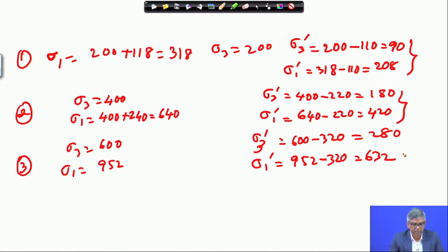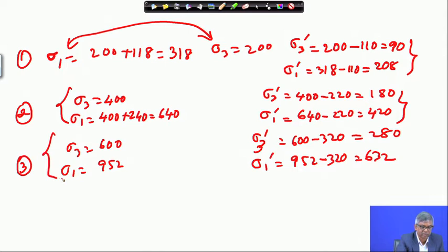So, we are getting sigma 1 and sigma 3 in terms of total stress, one set for each test. That means I get 3 circles, 1 circle for each. If I draw these 3 circles, they represent the total stress circles, and if I use the sigma 3 dash and sigma 1 dash and draw other circles, by using these I get another circle each. The circles based on these will be the ones representing effective stress.